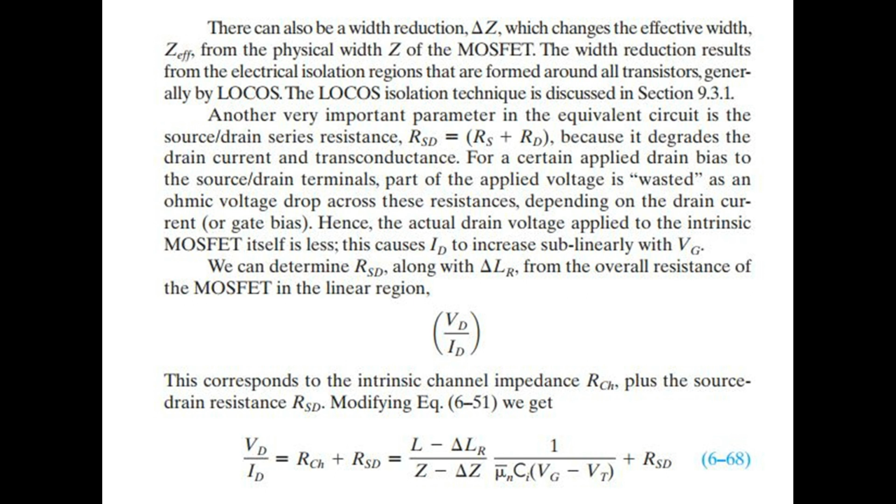We can determine R_SD, along with ΔL, from the overall resistance of the MOSFET in the linear region. This corresponds to the intrinsic channel resistance R_ch, plus the source/drain resistance R_SD. Modifying Eq. 6.51, we get Figure 6.40.